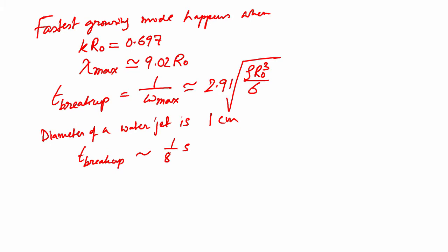Okay. So, this much is the Rayleigh-Plateau instability, and this is the fundamental mechanism by which a liquid jet breaks up, even in absence of any quiescent air, even in absence of gravity, even when there is no viscosity in the liquid. So, that means that a liquid jet is inherently unstable because of the surface tension forces present in the jet. It is a competition between pressure, surface tension forces and inertia forces that leads to the breakup of this jet at a characteristic length scale. Okay.